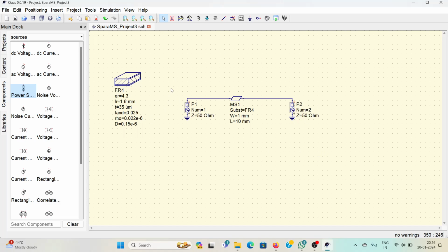In my previous video, I used the ideal model of a transmission line. Now microstrip line is also a type of transmission line. It is a transmission line, but it is fabricated on a substrate. It's etched on a substrate, and it has various properties, like it has losses attached to it, because we will have some kind of fringing fields coming out of the transmission line.